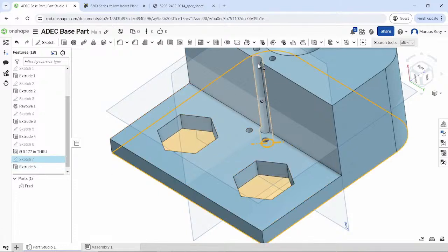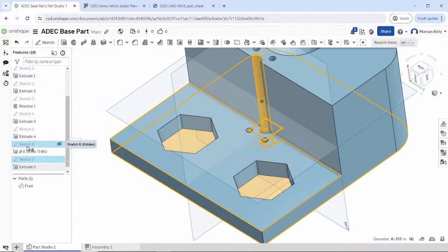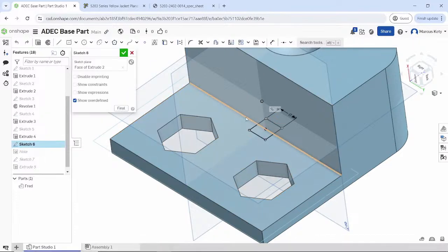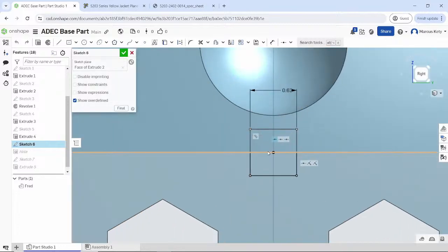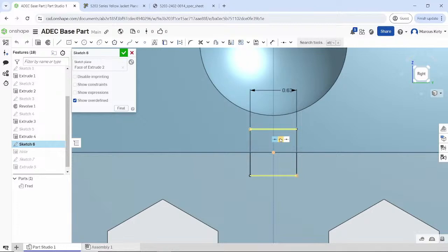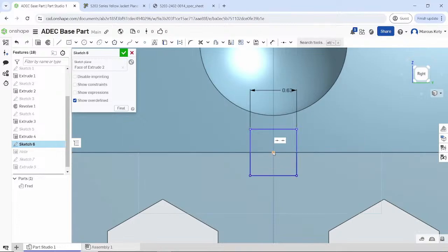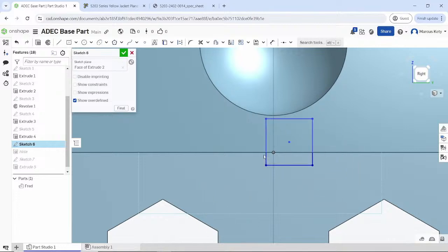If I wanted to move where this motor is, I can come into this sketch. I've selected too many sketches. I can come into this sketch. And right now, this was attached to the origin whenever I made it, and I can see that because right here it is showing me that the origin is what I have been attached to. So I'm going to click that, I'm going to click delete, and it immediately underdefines everything because it doesn't know where in space I want it to be.